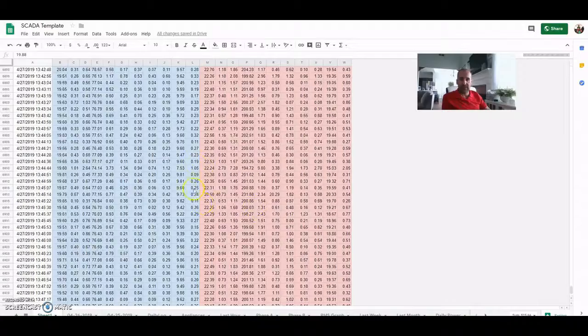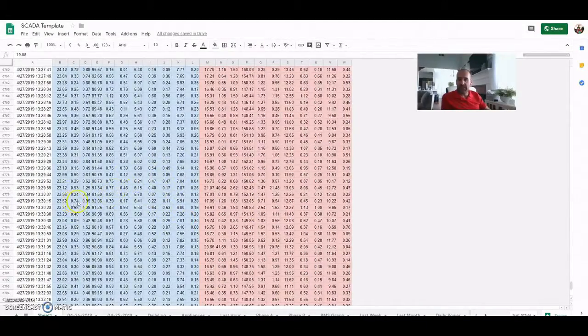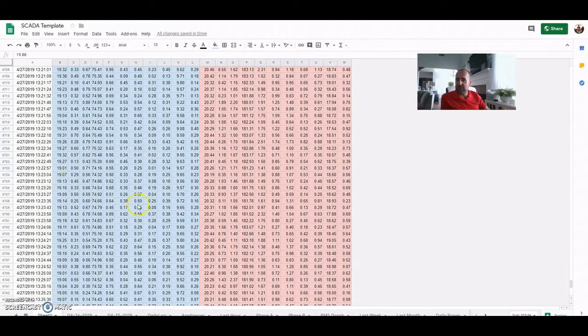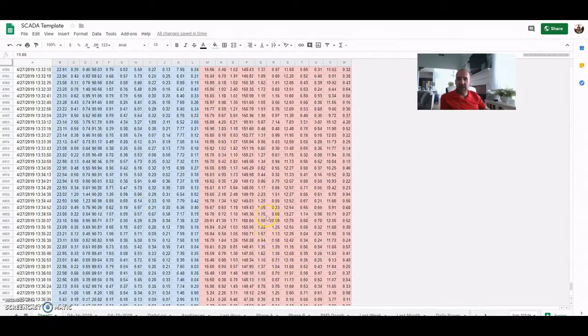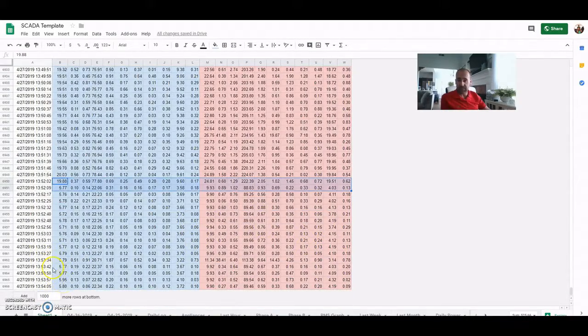So as you can see here is the data coming from the Photon. You've got two phases in your house, the blue and the red for phase A, phase B. There's a column for the RMS current, and then columns for whatever user-specified frequencies you want to look at. So you can see we have samples coming in about every 8 seconds. And for example, right here where I've highlighted, you can see the RMS current drops on both phases. So that's the downstairs air conditioner shutting off.